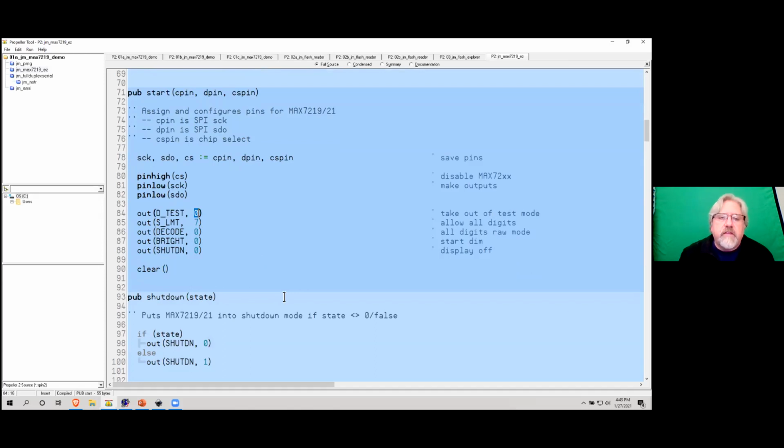You already have it if you did the download today. Anyway, you'll need to look at the register values that are allowed. So for example, even though the code handles it, the brightness register goes from 0, which is the dimmest value that's displayed, to 15, which is the brightest value. So you have 16 levels of brightness in there.